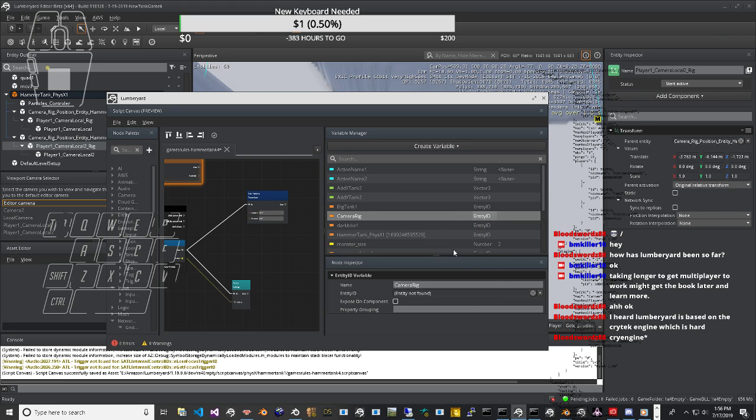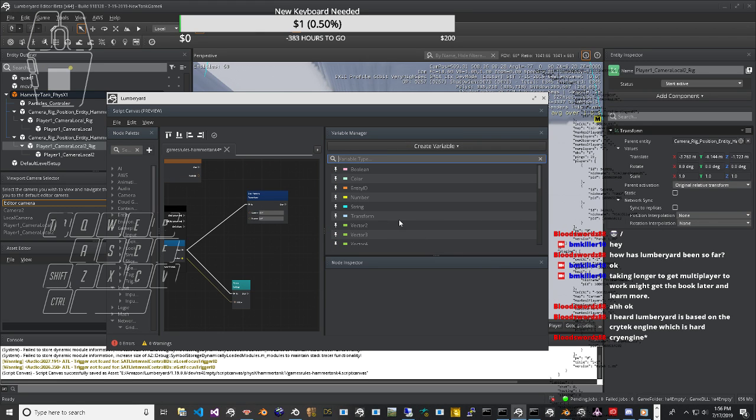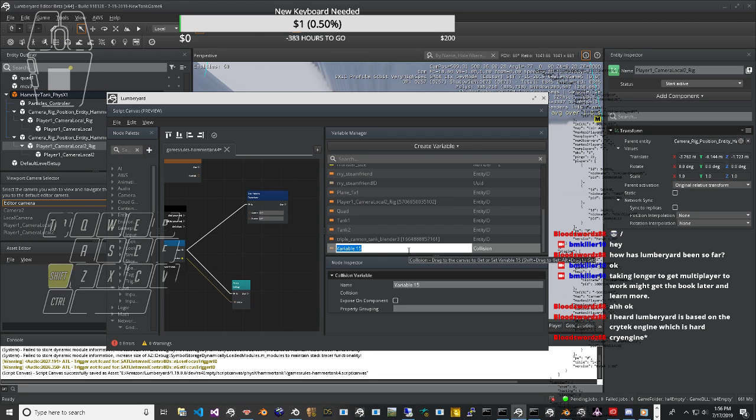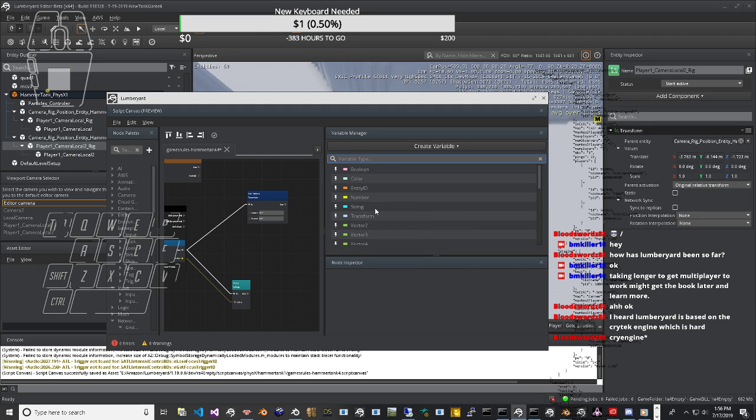One feature of orthogonal matrices is that their inverse is their transpose, that is, the matrix derived by flipping everything about the main diagonal running from upper left to lower right. In the small angle approximation, the right-hand side is very close to the unit matrix because the squares of small angles are smaller. Yet with the inverse matrix we can convert from coordinates in ROAD to coordinates in Earth. The last set of coordinate frames is WHE.